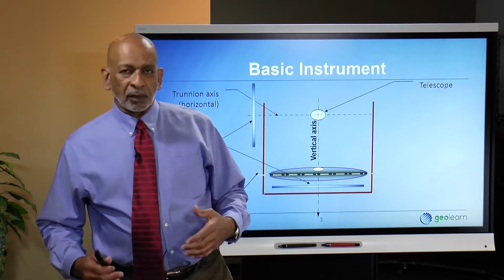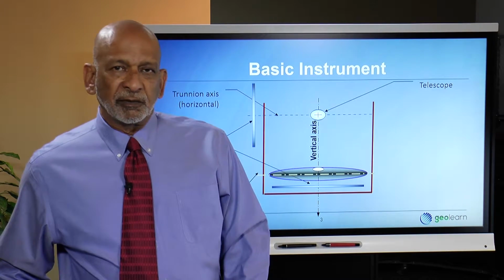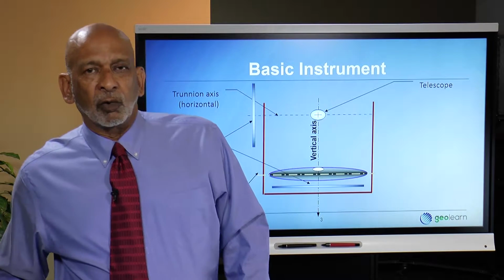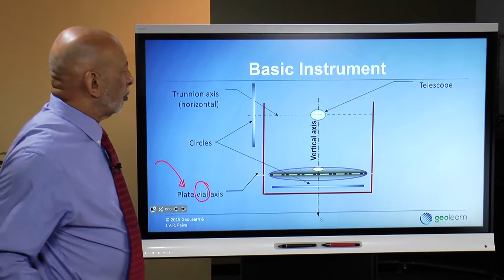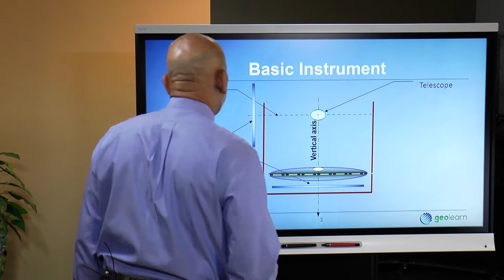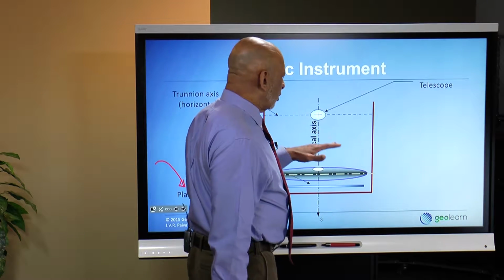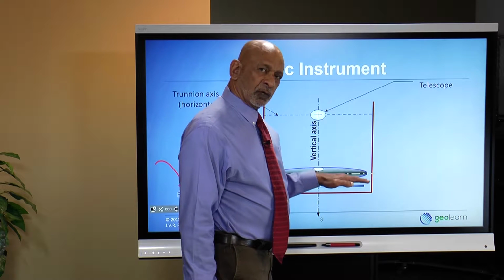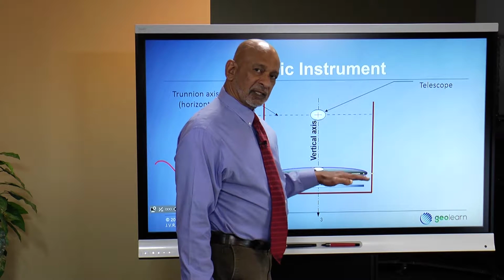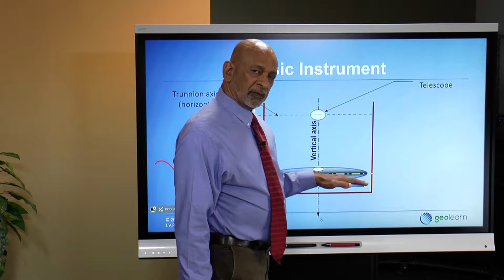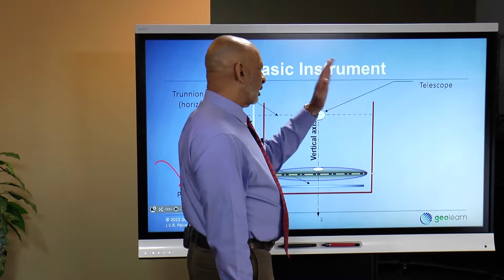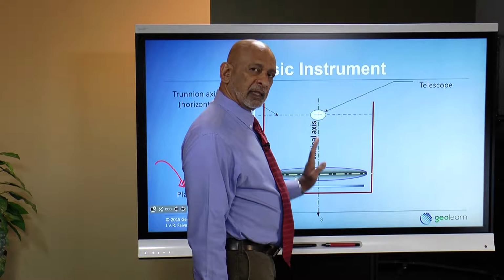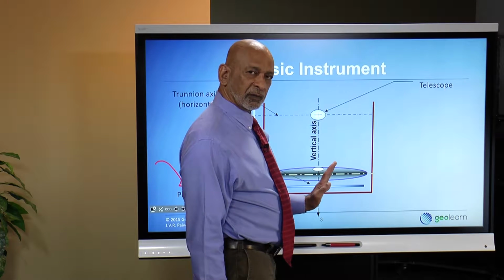As you may remember, the horizontal is always defined as being perpendicular to the direction of gravity, or the vertical. So by attempting to get this bubble centered, what you are doing is making the leveling vial's axis horizontal, and then if it's properly adjusted, that would mean that the mechanical vertical axis of the instrument is vertical and therefore aligned with the direction of gravity.